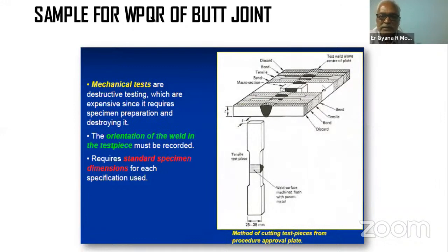So after taking out these components, in the bent pieces, we grind the top off. Whereas in tensile pieces, we also try to grind it. We grind off the top protruding portion, and then we have a piece like this. Now this goes in for the testing. So collection of the pieces is also done this way, and it is desirable to have it this way only.